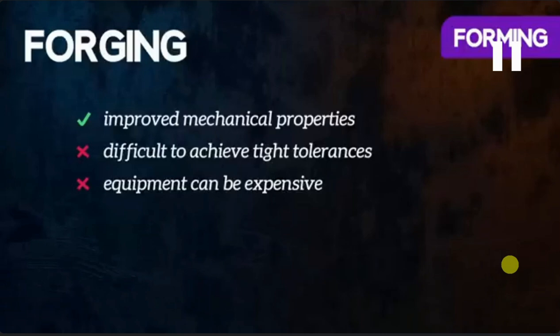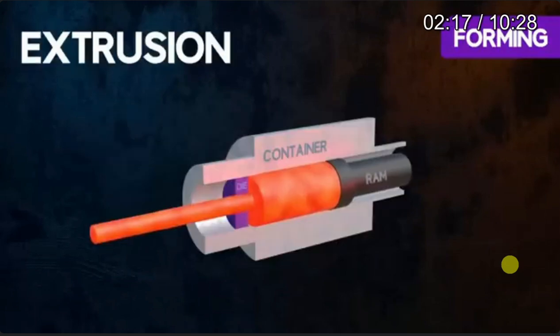Yes, these are the advantage and disadvantage. One, the mechanical properties improve because we heat above the recrystallization temperature. But the tolerance cannot be achieved easily, because it requires a large force that cannot be easily applied. And the equipment we are using is quite expensive.